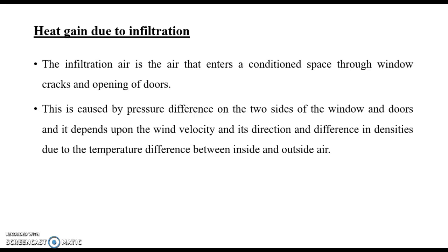Due to these openings, the air pressure difference causes air to enter from outside to inside of the conditioned space. This is due to the pressure difference on two sides of the windows and doors, and it also depends upon the wind velocity and direction, and the difference in density due to the temperature difference between the inside and outside air.